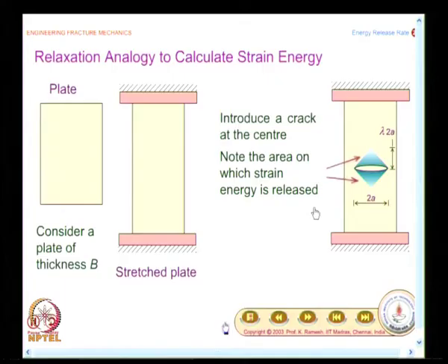See, in fact, even in your design courses, when you develop how to understand the concept of shear, suppose you take a shaft and put a keyway and put a key there, which is subjected to torsion, and you want to visualize that shearing action takes place on the keyway. If you are given a strong metallic key, it is difficult for you to visualize. One of the tricks that is employed there is, imagine the key is made of frozen butter. Then you can visualize when the shaft is twisted, you will find that shearing action takes place. You are able to feel it with the component in question.